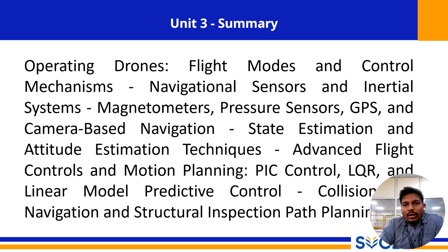This is particularly critical for altitude estimation, where the EKF fuses the smooth but drifty data from the gyroscope with the stable but noisy data from the accelerometer to produce a clean altitude estimate that is robust even during aggressive maneuvers.